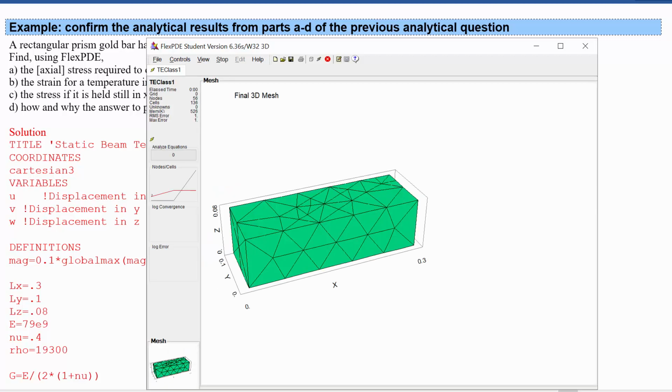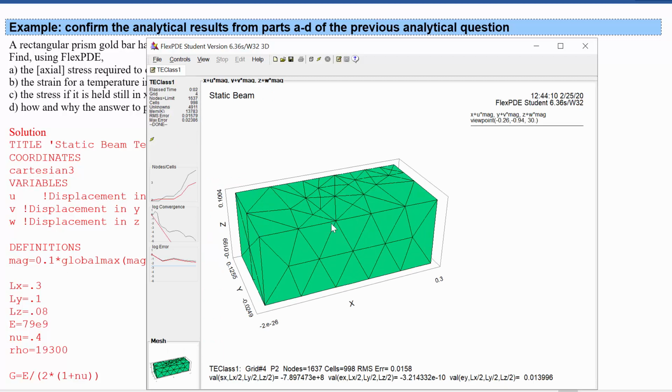So here we've got it just fixed in X on the X surfaces, 790 megapascals. We got a lot of Y strain going on there. And imagine we incorporate a little bit more realistic of a loading condition where it's not just fixed in the X direction on this surface and this surface. That would be if it can slide in the other directions. Maybe it can extend there. It's not rigidly supported on this wall.